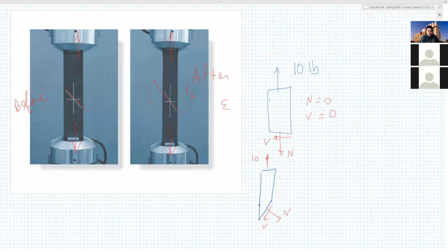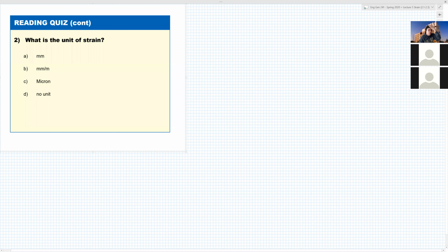All right, so let's go over real quick the units of strain. What are the units of strain? Normal strain. What is it? Change in length over what? Original. If your length is in meters, what do you divide by? Meters. Shear strain, right? Displacement, right? Shear strain is typically radians or angles. We're going to keep it to radians, and then if you want to convert to angle. So what are the units then for strain, whether it's normal or shear?